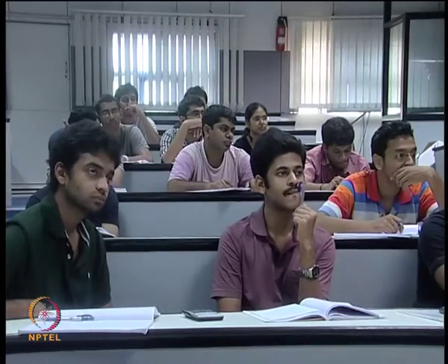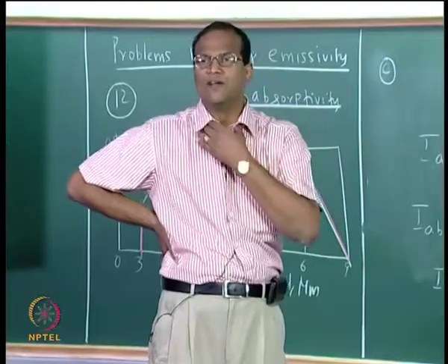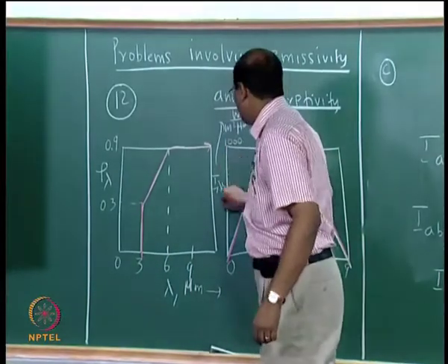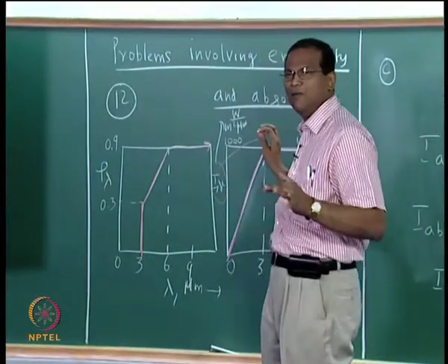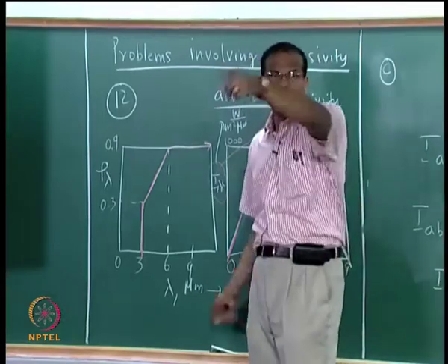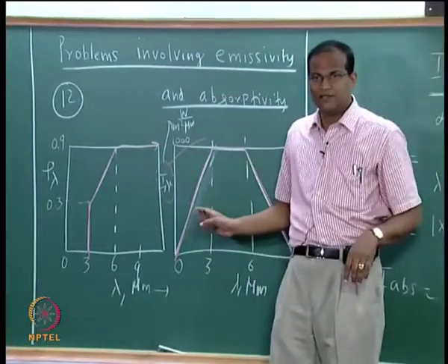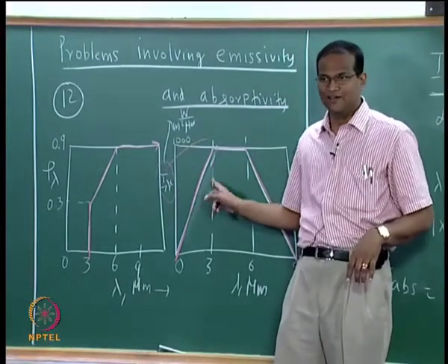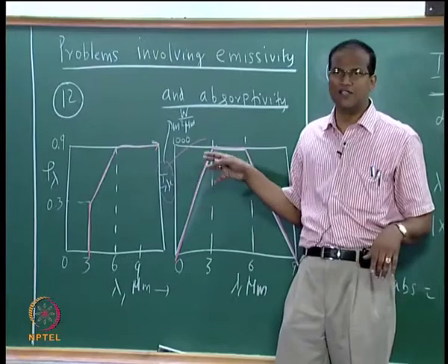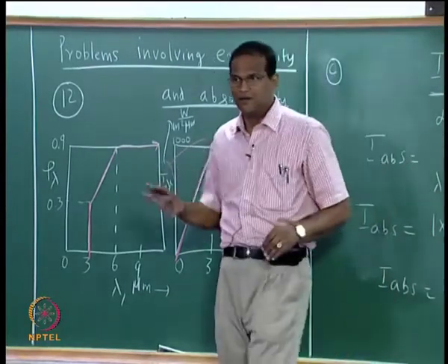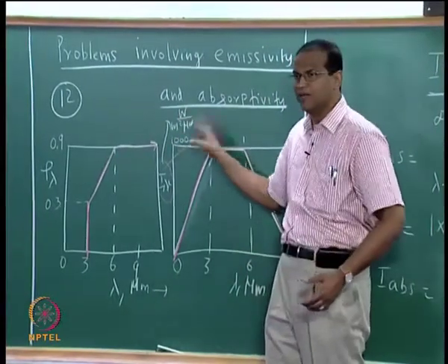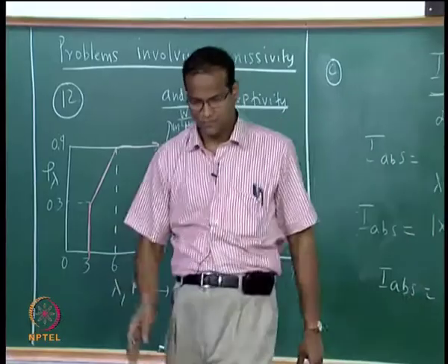He is saying that whether we should multiply by pi. So what did I do? No, I have taken the units of I lambda to be watts per meter square, otherwise you can keep it as E lambda, but we generally do not do E lambda. So he has a good point. Suppose I may just quietly put some steradian, then you are in trouble, but then I should tell you that it is diffuse and all that, right. Otherwise with this unit no problem, watts per meter square per micrometer into d lambda, micrometer gets cancelled.